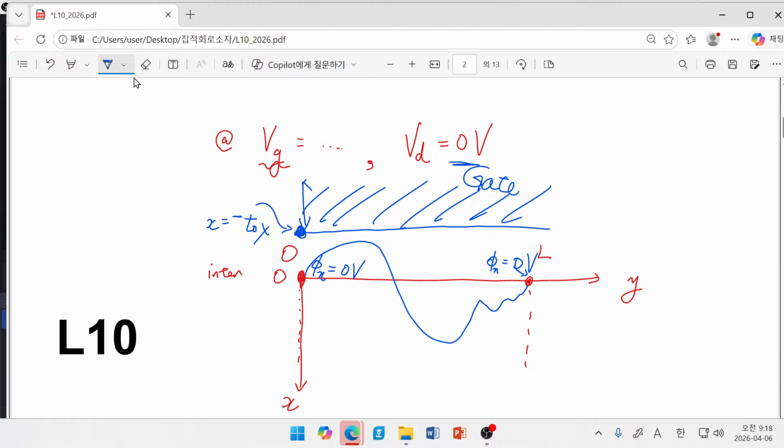If that is the case, then we will have certain current conduction, because current is obtained by taking the gradient of our quasi-Fermi potential. For example, here we have a non-vanishing gradient of our quasi-Fermi potential, and also here.